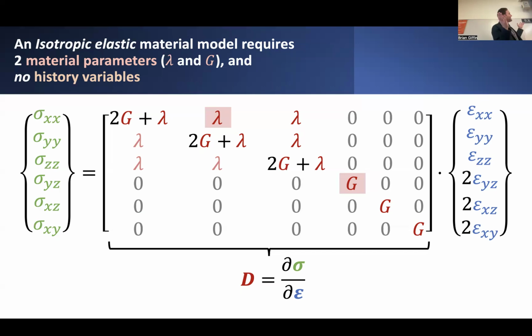But if you assume that the material only remains elastic, it doesn't degrade at all, then you would be perfectly content to just accept that there's no history dependence and it's just purely elastic behavior. Now, that's not to say that this is totally physical. Obviously, if you took this material outside of its reasonable bounds that it should operate in, if you know that the material in the real world should fracture if you took it to really large values of stress or strain, then clearly this model is no longer valid.